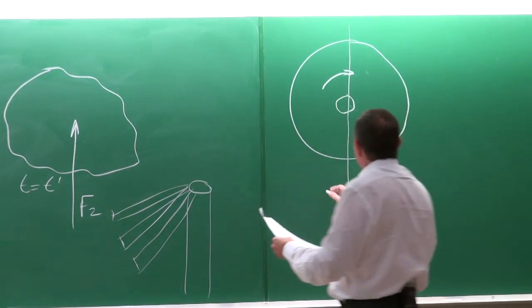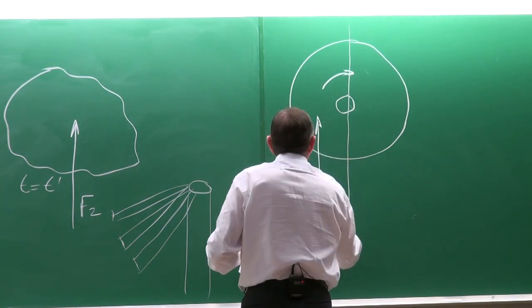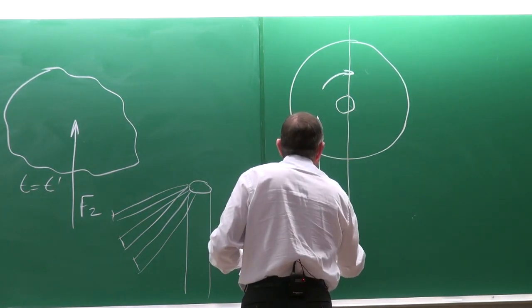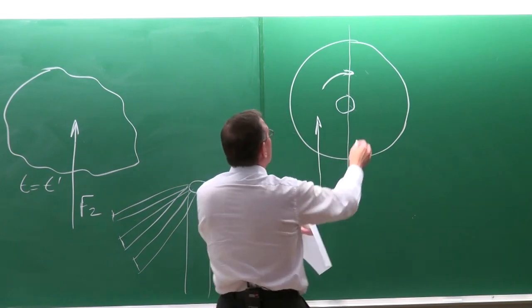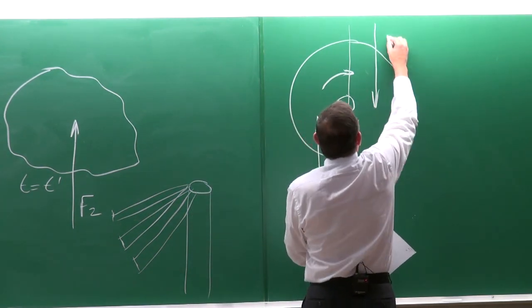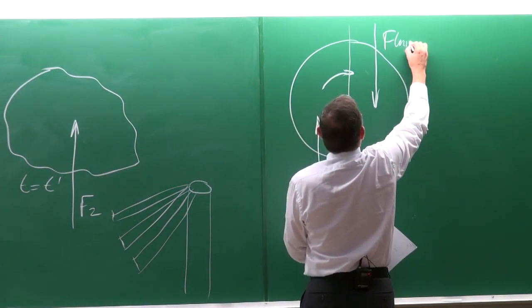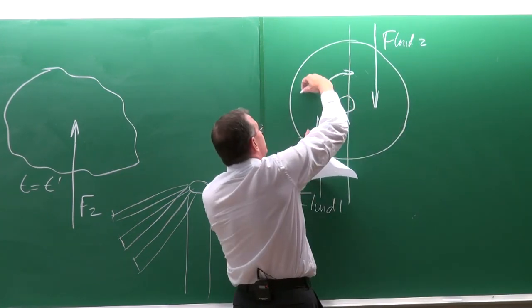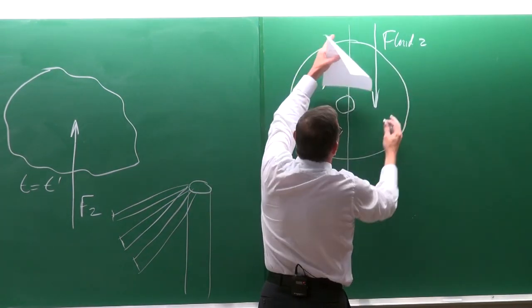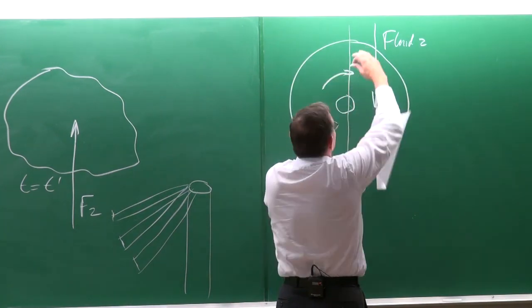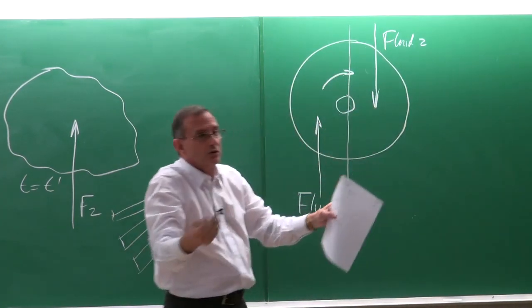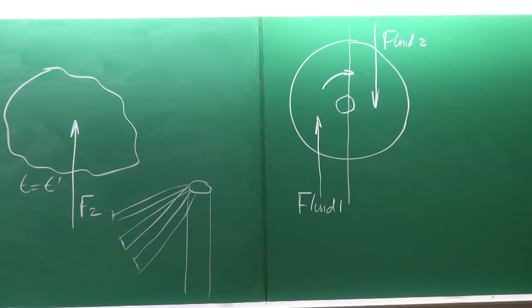Then we will have fluid 1 that would typically heat this porous media, and there will be fluid 2, and they do not mix. So here it will heat it, and the heated porous media will then go into the cold stream, and the heat transfer will occur on the cold side. Okay, so that is called the dynamic type, and this is called the static type of regenerative heat exchangers.